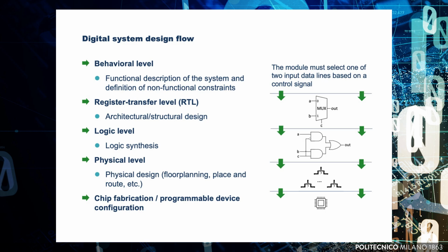The next step is logic synthesis, which is the main topic of this course series. Logic synthesis takes as input the register transfer description of the system, or in some cases, a behavioral description, and generates the corresponding logic circuit. After the logic level design, further processing steps are carried out at the physical level. Examples include floor planning, placement, and routing.